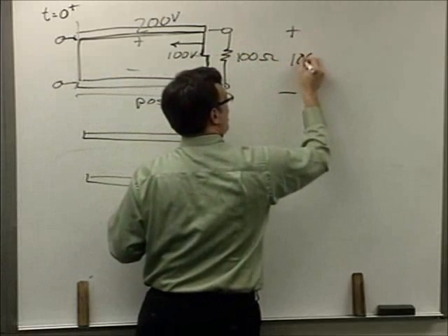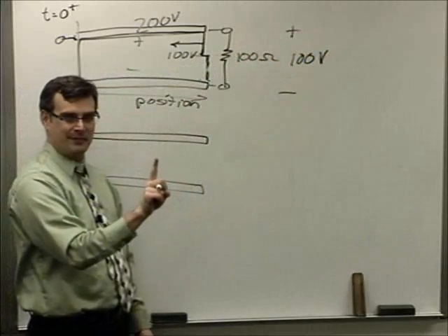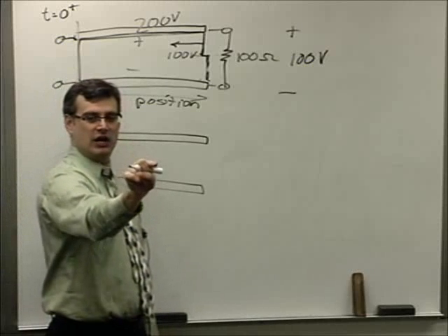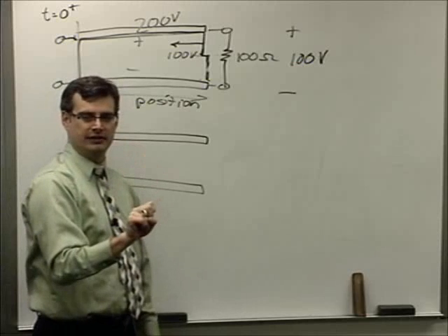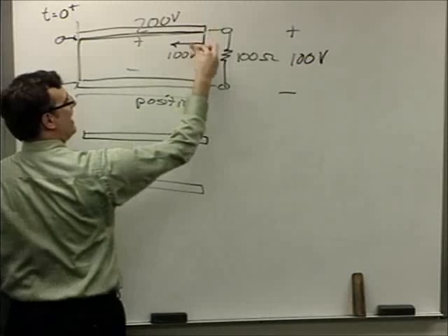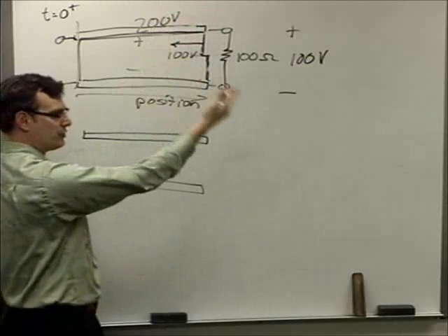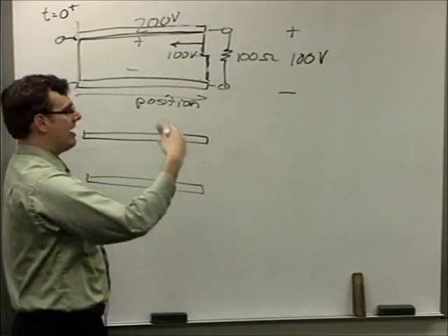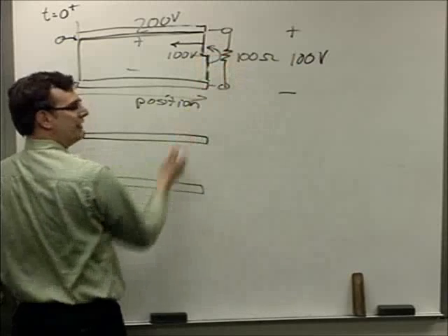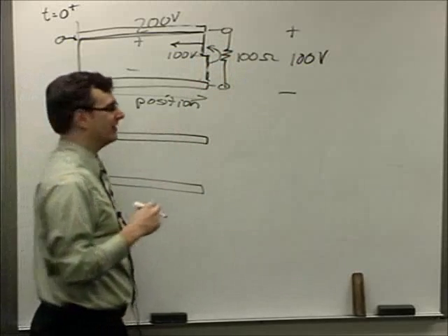So I'm going to get 100 volts across the load. Even though there were 200 volts on that capacitor, my 100-ohm finger is only going to experience 100 volts of it. And this extra 100 volts is going to erase across the line because it's your backwards propagating waveform, and there's nothing to feed it anymore. It's 0 at this junction because there's no reflection. I happened to pick a finger that was perfectly matched to the transmission line.